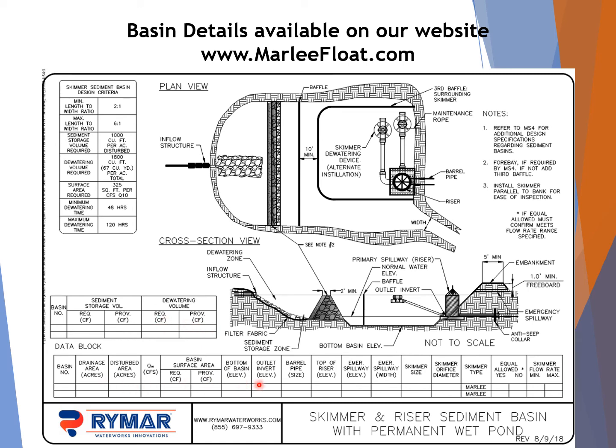Then we have basically all the other information you need for your skimmer basin design. So your riser information, your barrel information, skimmer invert, etc. Skimmer type, we filled it in for you. Here's the Marley, but you can certainly change that. And equal allowed, yes or no. And then the skimmer flow rate, again, you want to specify that range so that if a different skimmer is desired by the contractor, it's simply a shop drawing review.